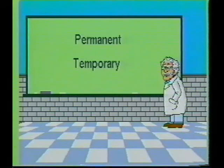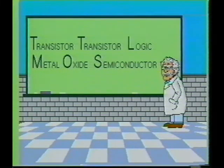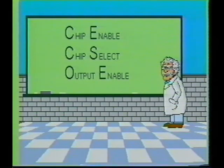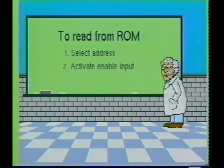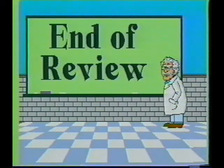There are two basic types of memory devices, permanent and temporary. The ROM is a permanent type memory storage device. Read-only memory devices are commonly available in both TTL and MOS configurations. The chip enable input is oftentimes referred to as a chip select or output enable input. To read information from a ROM device, the address must be selected and the enable input must be activated. This concludes review number 1.